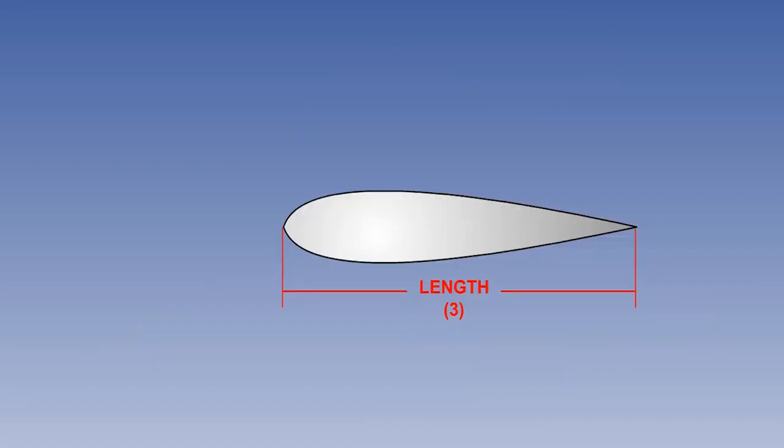The term streamlining is often used to refer to the smoothing of a vehicle's or aircraft's design shape, or the addition of fairings or fillets to modify it. But more specifically, it is the shaping of a body to keep separation as close to the trailing edge as possible. Streamlining increases the ratio between the length and depth of a body, reducing the curvature which induces an adverse pressure gradient.